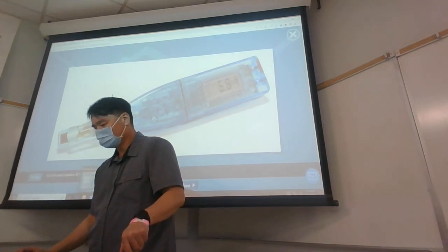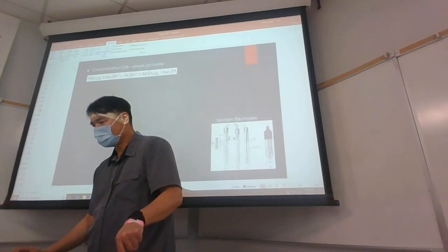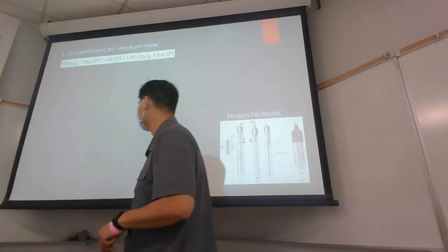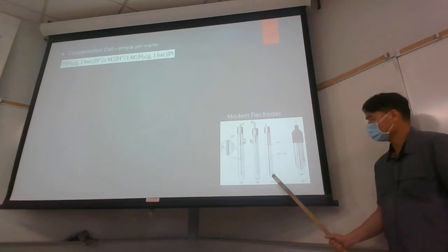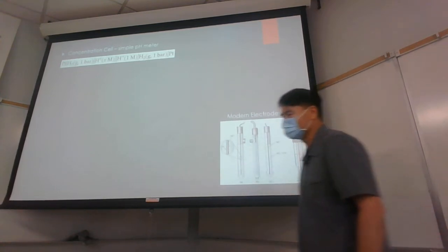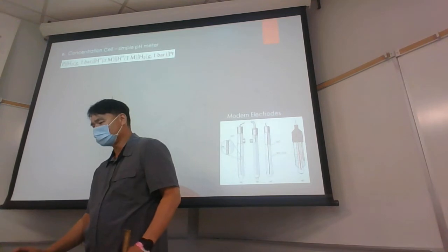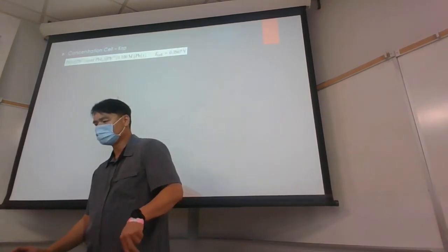The glass bulb, there's a gel on the outside of the bulb, and if that gel dries up, then the response from the pH meter becomes extremely slow. So that gel has to stay hydrated. And this is why these glass bulb pH probes have to be submerged in solution all the time. So once they dry out, they take a long time to rehydrate. And you'll have a very slow response.